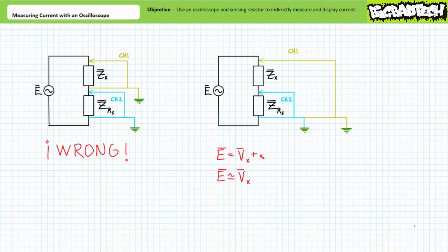Additionally, one can simultaneously display both channels to show the relative phase shift of the voltage across the element of interest and the current through it. This is the principal advantage of this technique and the reason I demand students get good at it. Recall that ammeters and voltmeters customarily limit themselves to the measurement of effective magnitude only and ordinarily do not measure relative phase shift. This technique, however, allows a technician to determine the relative phase shift between voltage and current.